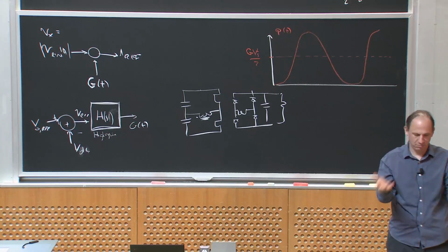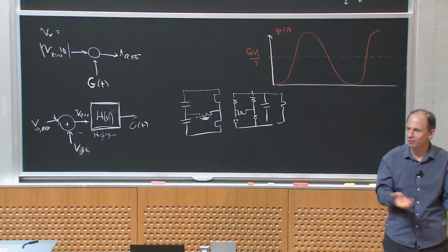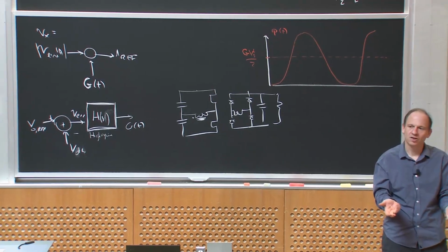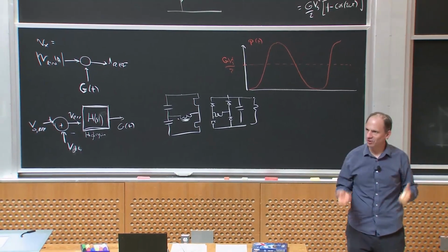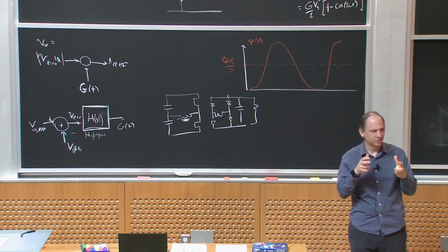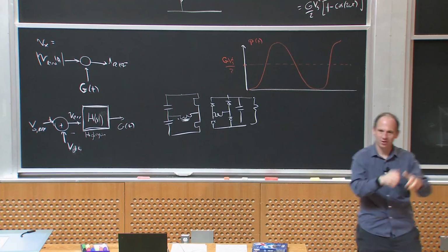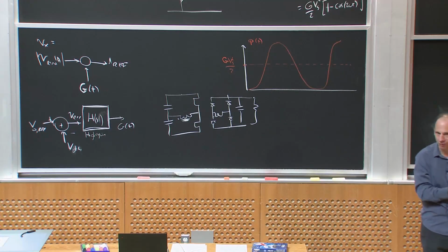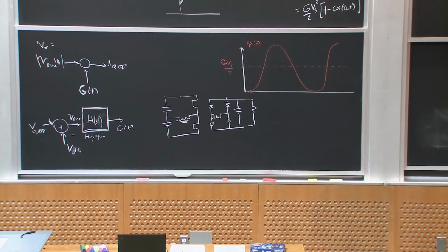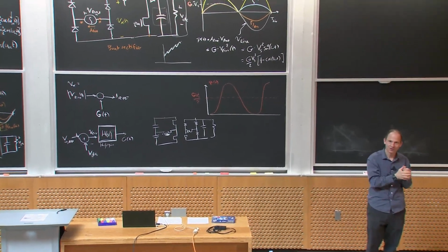And 400 volts is kind of standard, because it matches across all the different universal input voltages around the world for line inputs. And as a consequence, you can get really good energy storage capacitors and a bunch of other really good, cheap elements to build your converter there. And so then you have two stages. You have a first stage that does that. Then you have a transformation and isolation stage, which gives you some low voltage, typically 12 volts, but it can be other voltages in servers and things like that. And then you have usually another converter that's more or less a buck converter or some variant that gets you very high bandwidth control over your microprocessor supply. So hence you can see we're going through lots of power conversion stages here.